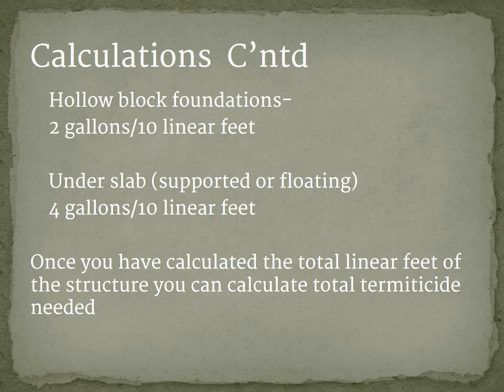The bottom line is, let's say you're on the outside, you do a trench along the foundation. It takes you 2 minutes to treat that trench with the termiticide at the rate of 4 gallons per 10 linear feet. My question for you is, when you need to treat the hollow block and you drill into the hollow sides of each block, how many seconds would you spend treating that hollow block on the same 10 linear feet? Well, it's a simple mathematical equation, but the bottom line is that if it takes 2 minutes to treat the 10 feet with 4 gallons outside, you're going to treat 1 minute to get the 2 gallons per 10 linear feet on the hollow block foundation.